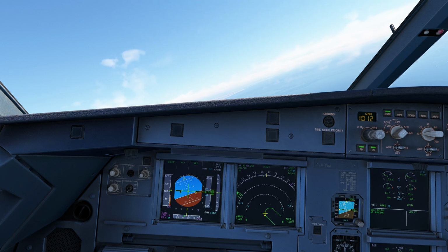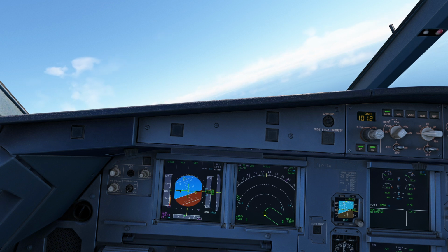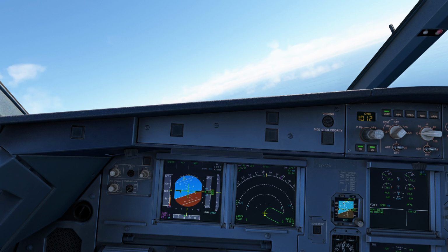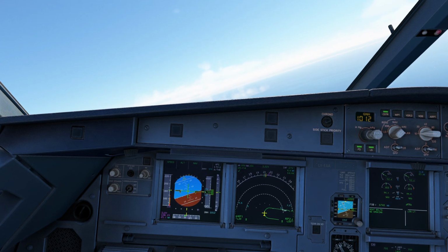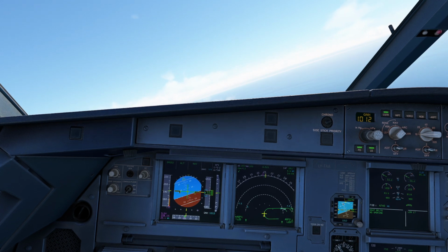Then the aircraft will track the localizer using LOC mode, but the pilot must visually correct for runway alignment once visual contact is made. Autoland is not available on offset ILS approaches. These approaches require manual landing once visual cues are acquired.